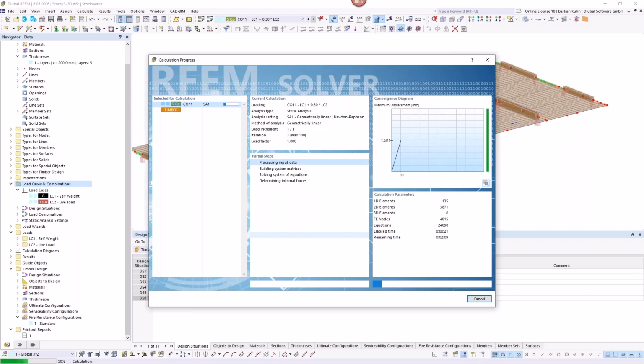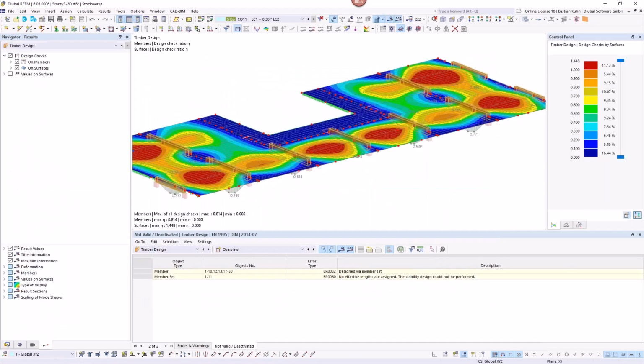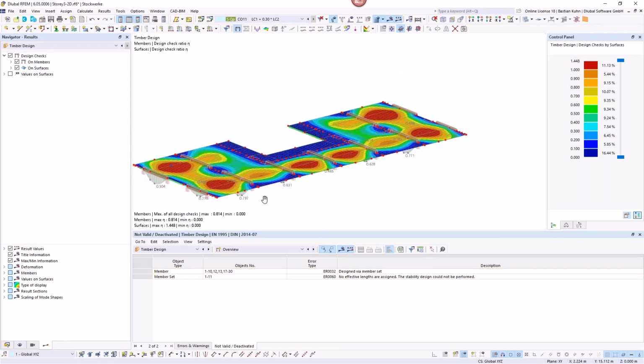You know, the simplified vibration analysis is similar to the SLS verification, looking at where the biggest deformation is, and this is then divided by the limit deformation of 5 millimeter. I showed it to you in the configuration settings, and you see everything's red. That's not nice.